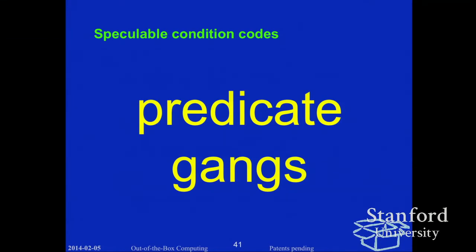And when you are doing a whole bunch of operations in parallel, all of whom set the condition codes, well, who wins? Who does set them? And so condition codes are never used in wide issue machines. In an out-of-order machine, condition codes have to be renamed because of the problem that they will get cluttered. The add and the subtract are not necessarily done in the order that they look like, and you have to have multiple copies of the condition codes that move around like multiple copies of the registers, and it's part of the extremely complicated and power-hungry part of making an out-of-order machine work.